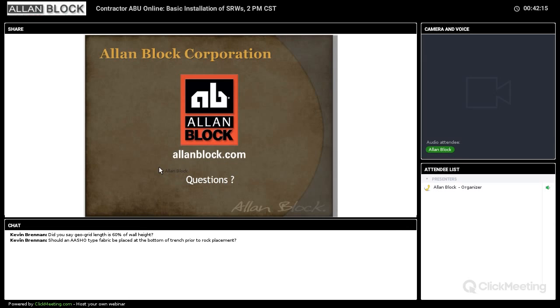If your engineer has said that your soils that you're trying to build upon are soft, then they might recommend some sort of filter fabric, embankment protection fabric, some sort of textile to help when you place the rock and you compact, that rock doesn't just get squished into the clay. So it would definitely depend on the project. But good question.